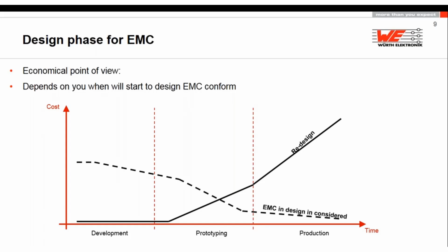Many people say we don't have space. Okay, there's always a way. 0201 size may be difficult to solder by hand, but sometimes there's space for 0603, and some people can even solder 0402 by hand, but I would definitely go with 0603 or 0805.